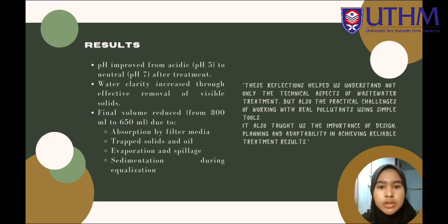However, we observed a reduction in water volume, from 800 ml initially to 650 ml after treatment. This loss happened because some water was absorbed by the filter materials, while other amounts were lost due to evaporation, trapped solids, and spillage during transfer. Despite this, the overall process successfully demonstrated basic wastewater treatment on a small scale.